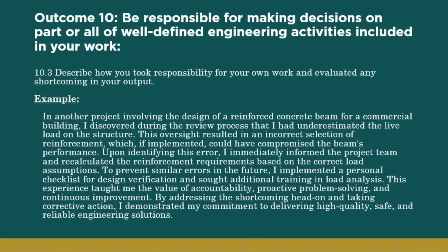In another project involving the design of a reinforced concrete beam, for example, for a commercial building, I discovered during the review process that I had underestimated the live load on the structure. This oversight resulted in an incorrect reinforcement, which, if implemented, could have compromised the beam performance.